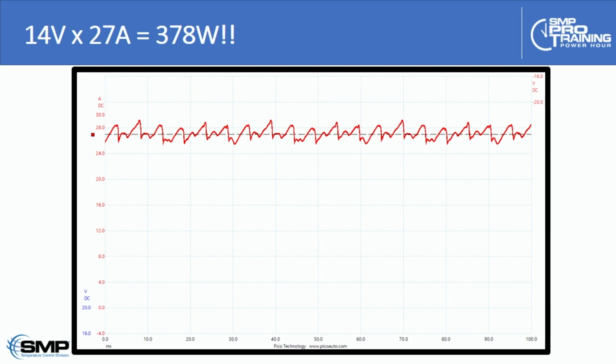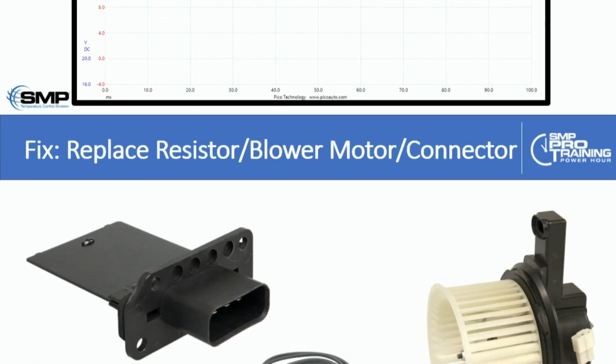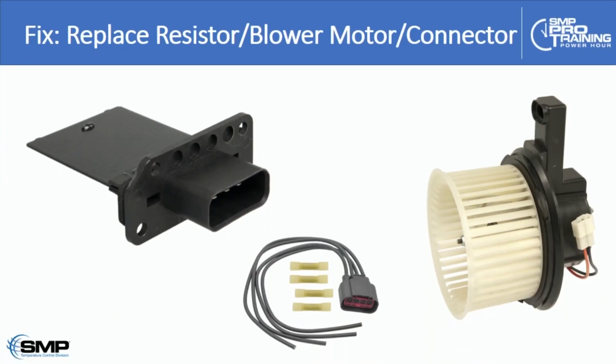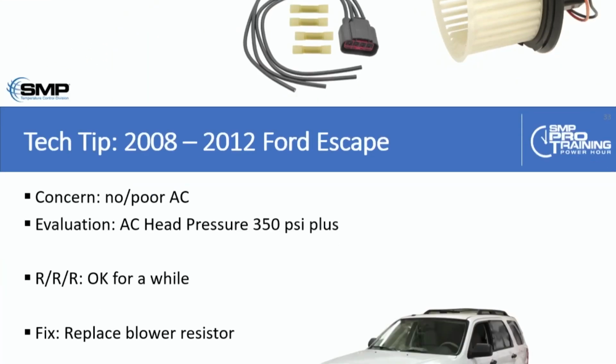And you're going to have repeat and rapid blower motor resistor failure if you keep putting new resistors into the same vehicle with this blower motor. So oftentimes the fix, that's why for popular vehicles with high pattern failures, we typically make the resistor a high temp blower pigtail, and the blower motor available as a kit assembly.